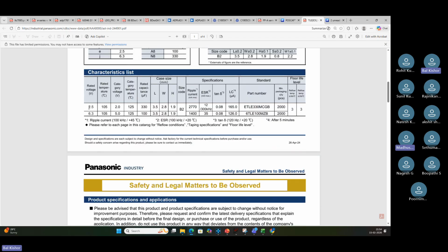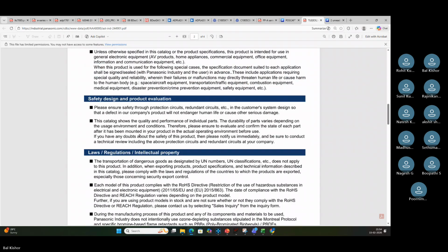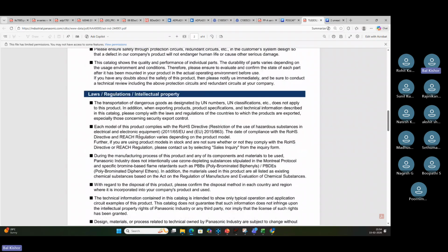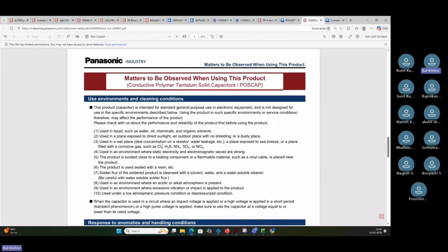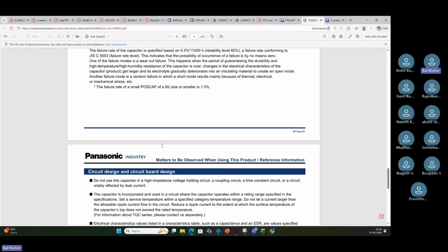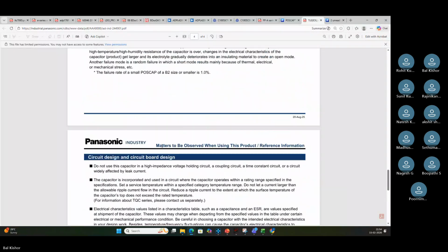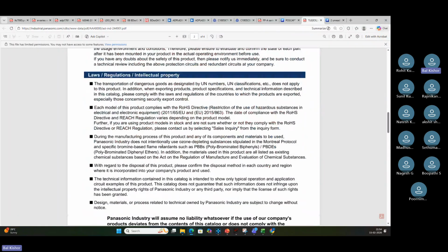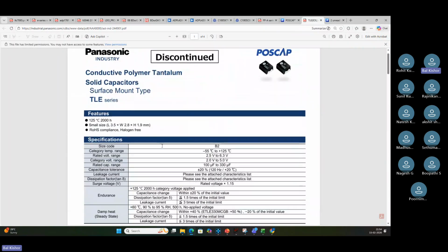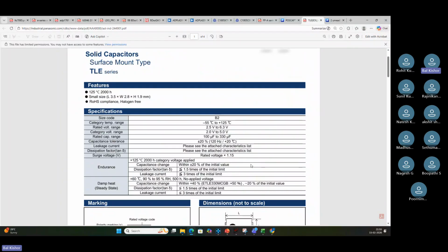And you can see, let's say 2.5 volt rating, so you will have to use it for a 1 volt application, maybe. Even if you want, you can go ahead with 6.3 volt also for a 1 volt or 1.5 volt application. And mostly processors need these capacitors. Okay, so polymer capacitor, I think you now have a little bit better understanding.